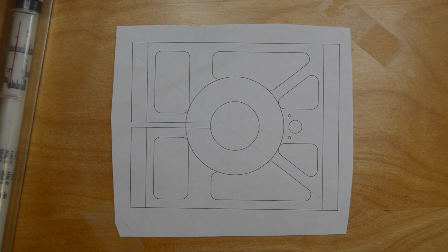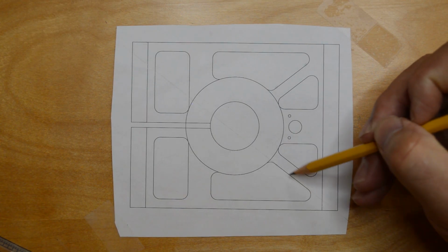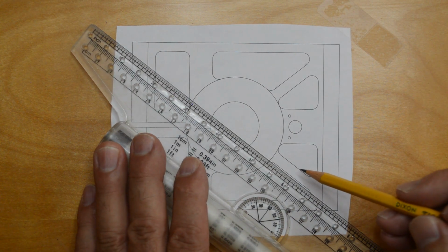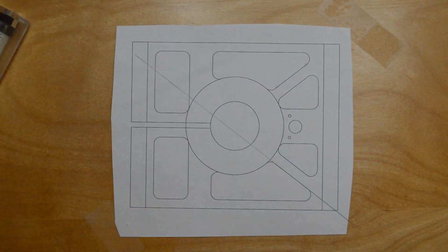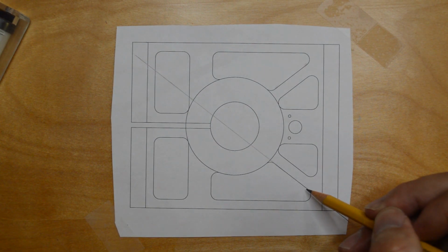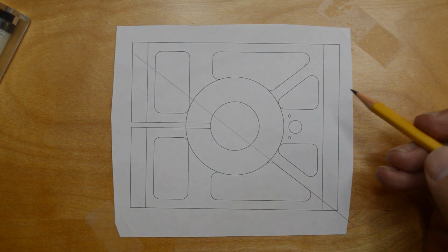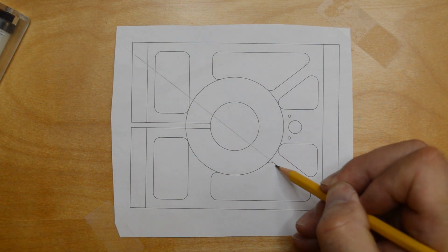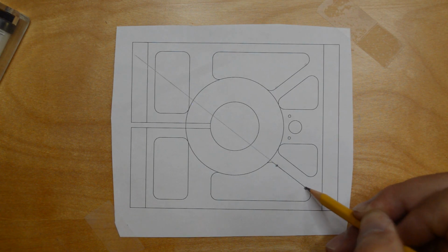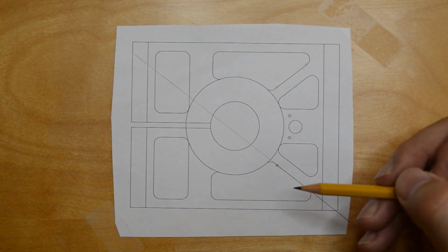Okay, the next definition is going to be for the endpoints and the midpoint of a line. So take this CAD part model, for instance. So as you know, a line, let's say this one, for instance, mathematically speaking, goes on forever in either direction, right? But in CAD, it's actually only drawn from some point here to some point here, and that's actually at the tangencies of these arcs, right? So in the CAD database, in other words, the DXF file, this line is stored as XY, XY, okay?